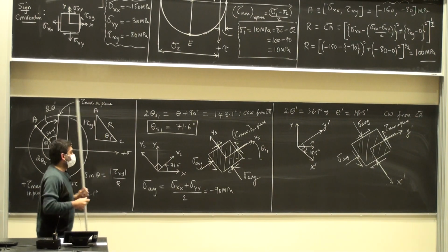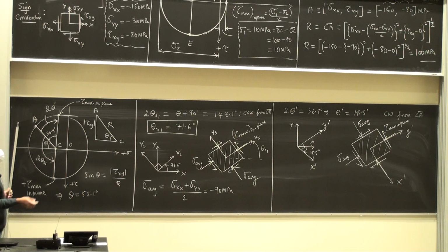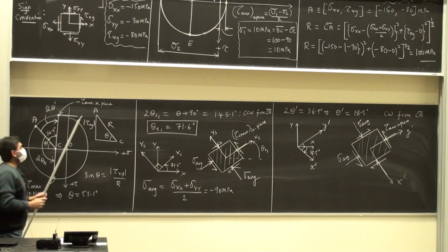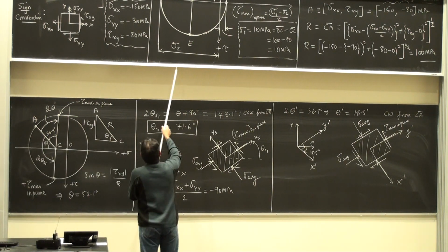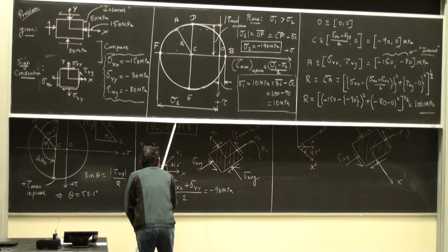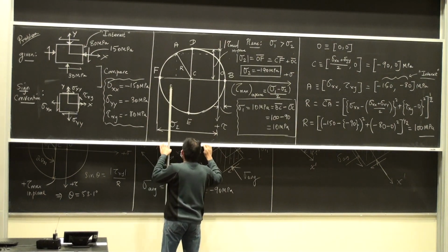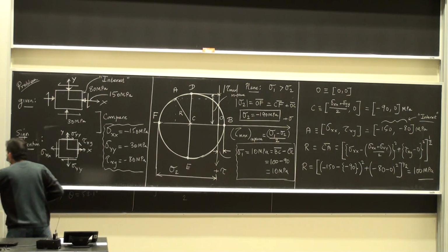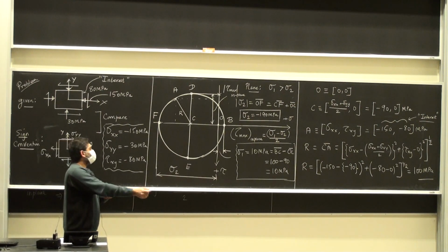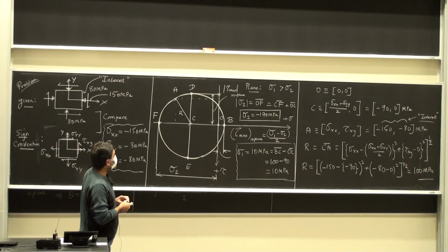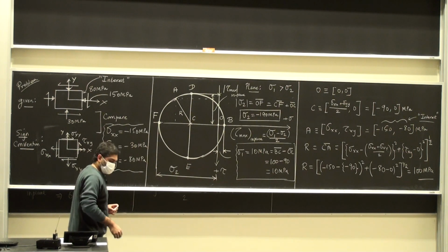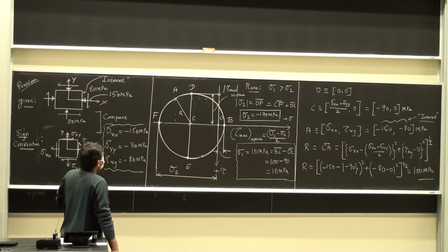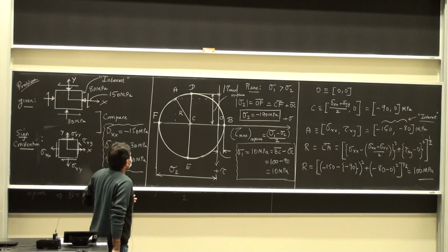And the problem is one has to arrange these in the order sigma 1, sigma 2 and sigma 3 and then do it. But we don't have sigma 3. Sigma 3 is 0. Right? So let me make a correction there. Radius. Now, hang on. I think it's right. Because it should be sigma 1, 10, minus sigma 2, megapascals. So 10 minus negative 190, which is 200. Oh, yeah. That's right.